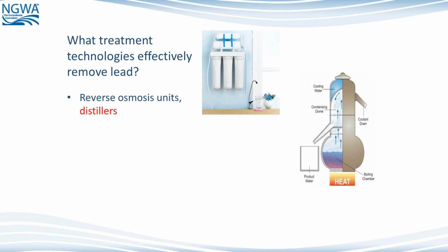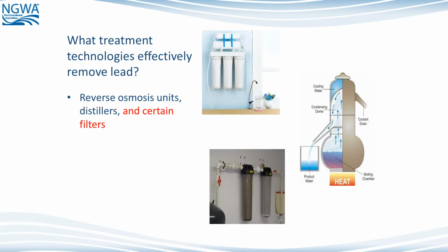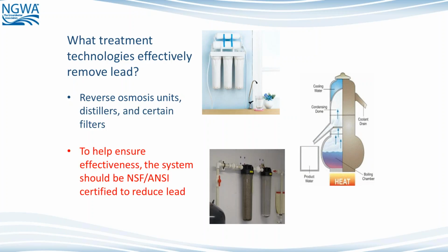Distillers will also work very well at this, as will certain filters that are designed just for the removal of ionic contaminants such as lead and mercury and arsenic. It's extremely important that whatever technology is used, that it be listed by NSF or meet NSF standards and be certified to remove lead.